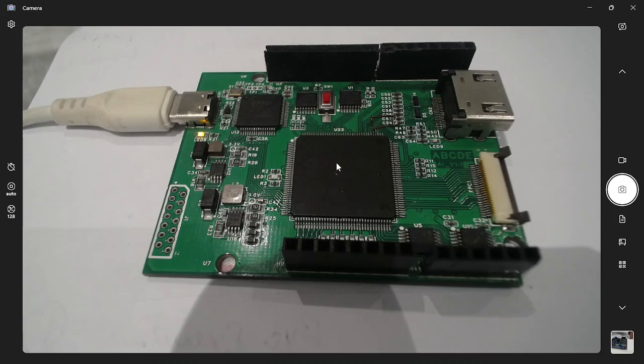SRAM is about 40 kilobytes, BSRAM is about 828 kilobytes, PSRAM is about 64 megabits, SDR and DDR are 64 megabits and 128 megabits respectively. It has 4 PLLs and 8 IO banks. These are the brief specifications of the processor which is on board.